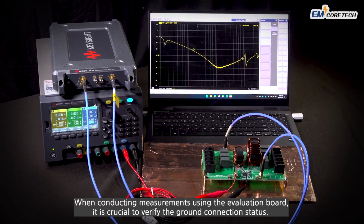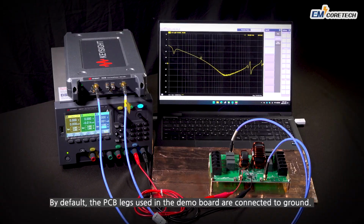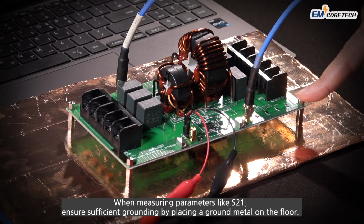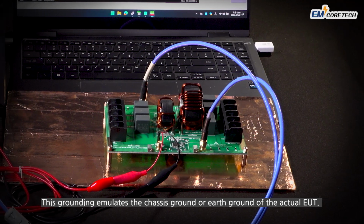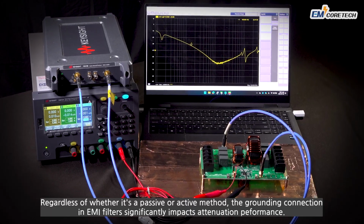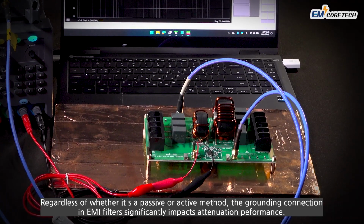When conducting measurements using the evaluation board, it is crucial to verify the ground connection status. By default, the PCB legs used in the demo board are connected to ground. When measuring parameters like S21, ensure sufficient grounding by placing a ground metal on the floor. This grounding emulates the chassis ground, or earth ground of the actual EUT. Regardless of whether it's a passive or active method, the grounding connection in EMI filters significantly impacts attenuation performance.